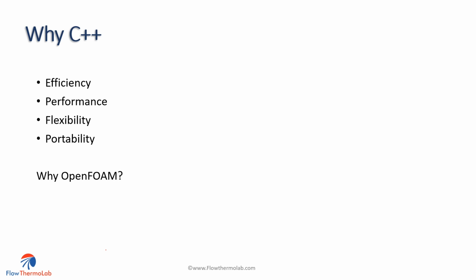And OpenFOAM's modular architecture leverages C++'s features to facilitate easy customization and extension of the code, which we'll see as we start going through this course. And we can implement new models, algorithms, solvers, or different components really easily in the grand scheme of things by writing C++ code and just slotting that in and integrating them into the existing framework without really having to have too much of a concern that we're breaking the rest of the code.